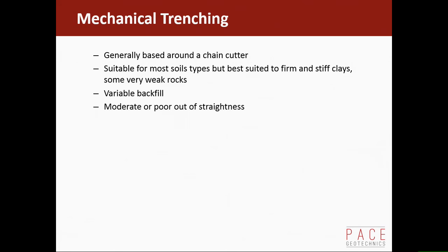So it's not great for backfill, and they tend not to be great for out-of-straightness as well in the trench profile. It responds poorly when you get a boulder in the trench, which is quite common in stiff clays, and you get an out-of-straightness incident. So they have their place, but they're not that reliable, not that great to use.